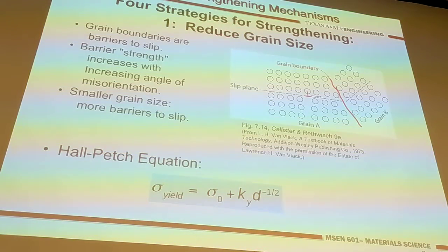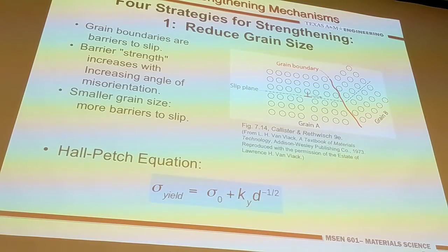In most cases, we're dealing with polycrystal. But we also mentioned that the deformation mechanism in metal is mediated by dislocation. So how fast or how easy dislocations move in the crystal matters. Therefore, in order to deal with the strengthening of metals, you have to think about how to deal with dislocation motion. It's very systematic.